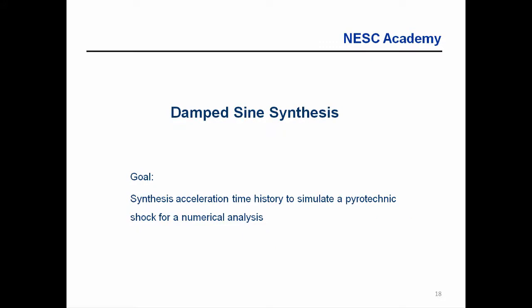Our goal in this case is to synthesize an acceleration time history to simulate a pyrotechnic shock for numerical analysis. Now that word simulate there I probably should have put in quotation marks. What typically happens is we'll measure field data, maybe from a stage separation test or flight accelerometer data, and we'll calculate an SRS from the acceleration time history, or maybe we'll take several and make an overall envelope. But anyways, we do end up enveloping our measurements, and then we add margin on top of that.